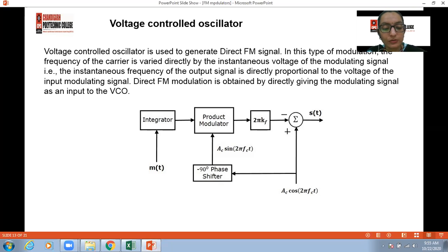That is for the generation, followed by a series of frequency multipliers and mixers, which is used for the configuration of VCOs. Such an oscillator provides very good oscillator stability, with constant proportionality between output frequency changes and input voltage change, and it provides the necessary modulator bandwidth to achieve wideband FM.